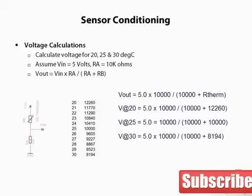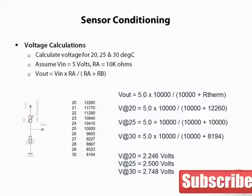So solving, we get V at 20 degrees C, 2.246 volts, V at 25 degrees C equals 2.5 volts, and V at 30 degrees C equals 2.748 volts. Now this is something we can use in our process. We can measure it with our A to D inputs and linearize through code, tables, or equations, and then move on from there.